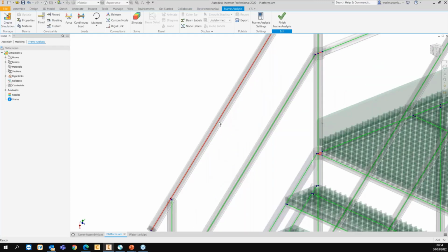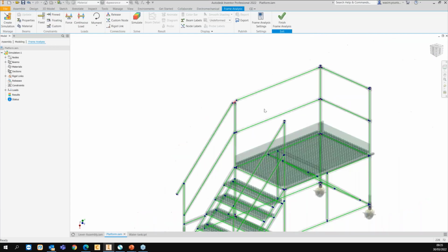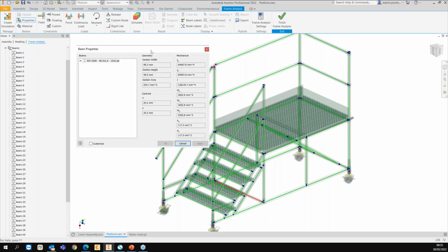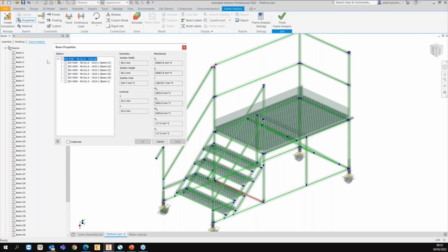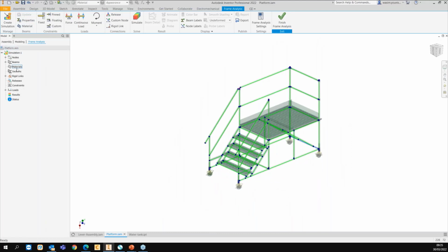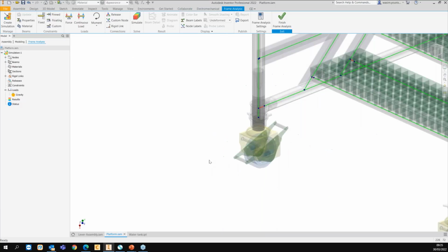And there we go. So every single green line there is now being idealized. So how do I know that? If I right-hand click on properties, there are your cross-sectional profile properties of that beam. So what we can do here is the same thing. So first of all, let's assign the gravity in the correct direction. Okay, it's in the wrong orientation. Let's go in the X, downwards.